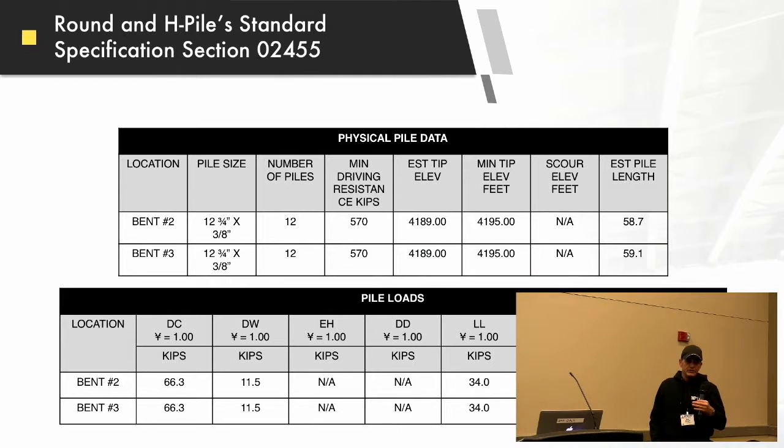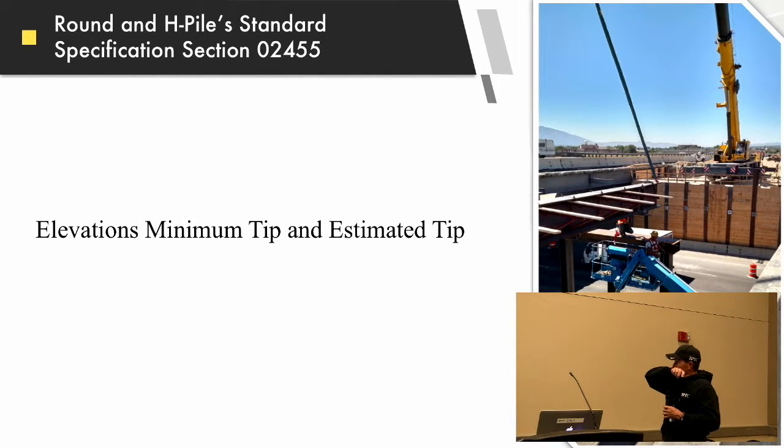You need to be right there on site watching what's happening with the hammer, with the piles, and everything that's going on, so that between you and the contractor you can decide, hey, we need to hold off and get the geotechs in here to see what's happening, so that we're not overstressing piles and then assuming that the pile is good and the capacity is sufficient for the structure in the end.